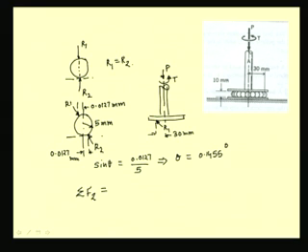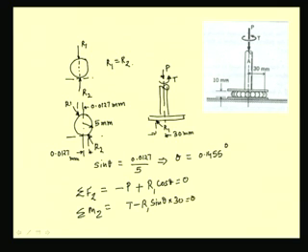When we write the force summation equation for this shaft, we have the sum of the vertical forces as minus P plus R1 cos theta equal to 0, and when we sum the moments, it is T minus R1 sin theta times 30 equal to 0. So from this we can find that the torque T that is required is 0.190 Newton meter. So this example illustrated how we solve for rolling resistance.